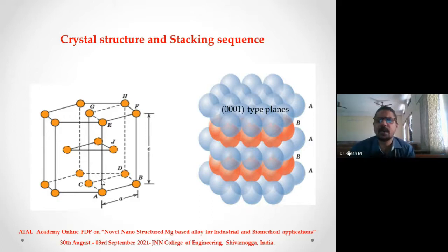One of the reasons why aluminum is such a wonderful metal is that you have 11 to 12 slip planes, which become active when you go to high temperatures. Whereas in HCP, you do not have a slip plane except for the basal slip plane, which needs activation. So unless you activate these planes, it will not get deformed. So conventional forming of magnesium is very tough, even though it is a light metal. They have an HCP structure.